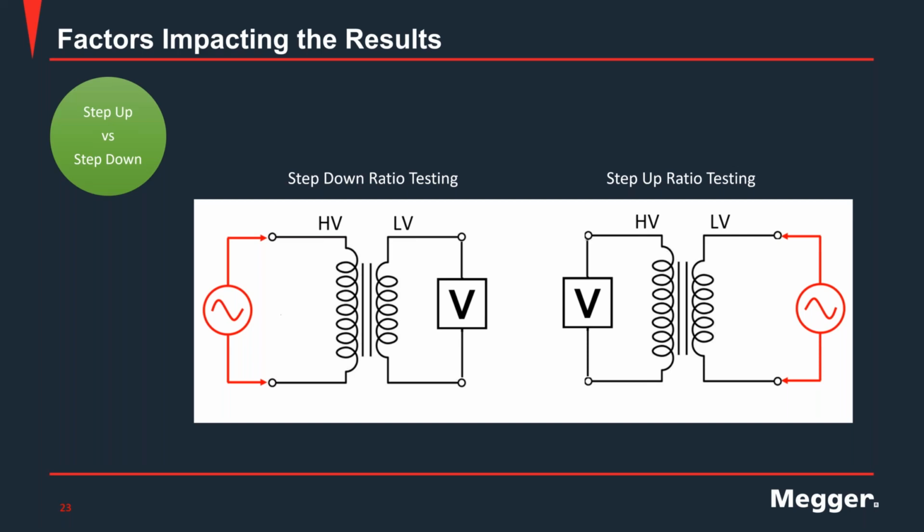So it's really important to highlight that if you want to do a step up, you need to have an instrument that is capable of doing it. Or you want to know and to limit that voltage on the high side, to safe levels both for the instrument and, more importantly, to the individuals involved in the test.